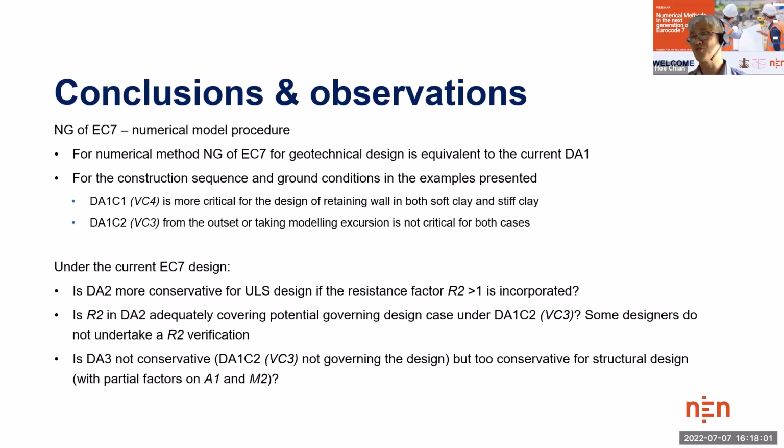For design approach 3, it is not conservative if you consider the geotechnical actions, but it is too conservative for structural design with partial factors on actions and material. So from that, you can see that between now and then there are changes in the next generation of Eurocode that you will need to start making when it becomes the replacement code in the future. That's all that I have to say. Thank you.